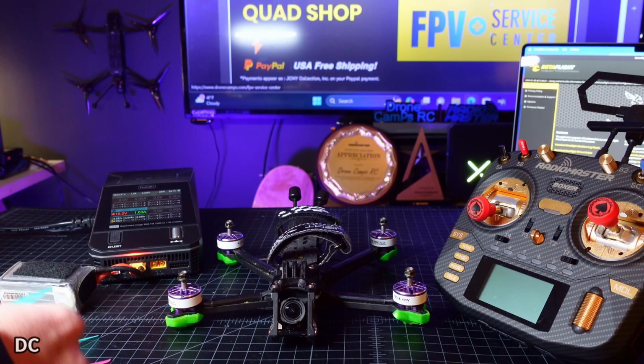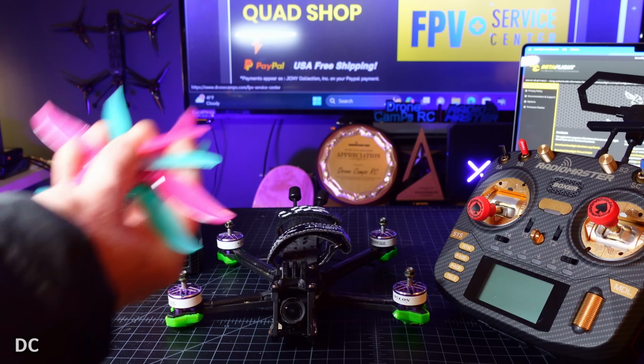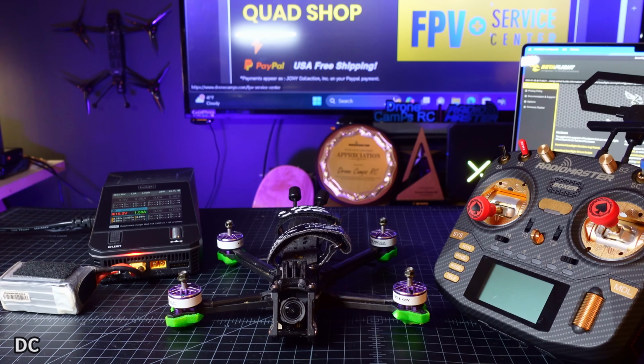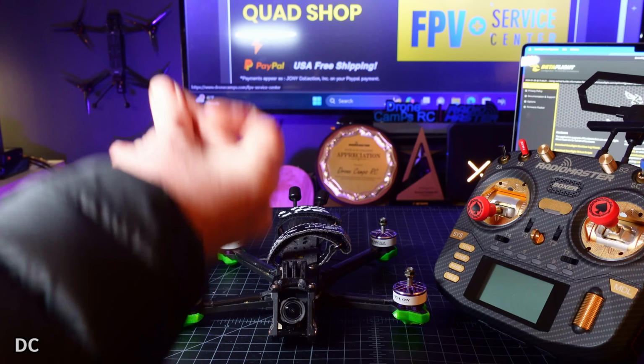If even one of these is on the wrong motor, what's going to happen when you go to fly your quad for the first time? It's going to flip across the ground. It could even, you know, I've almost had one hit the side of my Prius. It flew at my car and went under the car and out the other side. And it happened within, I mean, a split second, boom.